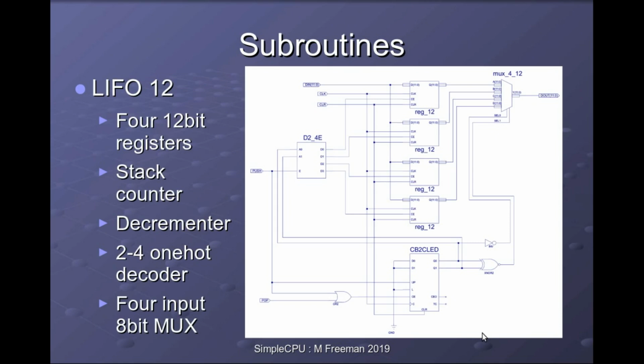So going back to our circuit diagram here, this counter here implements our stack pointer. So obviously that's a 2-bit stack pointer, and that is passed to the decoder. So initially that will be 0, so this will be giving 0, enabling the top one. Every time I push a value onto the stack, this counter will be incremented by 1, enabling the next register within that stack. To read off the values, obviously I need to decrement that stack pointer, and that's what our decrementing circuit does do. So if the current stack pointer is the value 1, this register will be enabled to allow me to push a new value on, but when I want to pop the value off, I want to read the value stored in the first register, and that is selected using this decrementer here to select that top input.